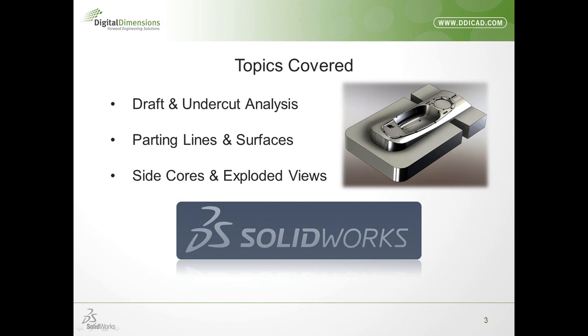The second part of it would be creating your parting lines and surfaces. And there's a lot of different techniques to doing this, but at the end of it all, whenever you're modeling, if you can keep in mind that the core of the mold tools are basically surface cuts and split lines. So if the tools themselves don't necessarily help you, you can always revert back to those fundamental tools and use those to get where you need to be. And then the third part of it is actually doing the tool split and adding things like cores and pins. And then we'll take a look at creating exploded views.